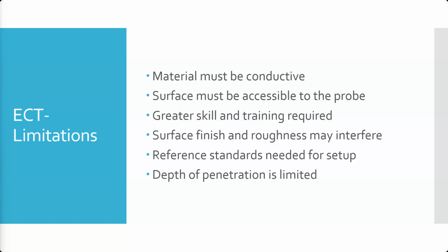The last part, depth of penetration is limited. So I said it can do surface and shallow subsurface flaws. Again, limited to about a half an inch. Some of your pipeline stuff can do real thick walled pipes, like 1 inch thick pipes. But at that point, you're starting to move more into what's called ultrasonic testing territory for getting that deeper penetration. So really, half an inch or less is typically where it's used.